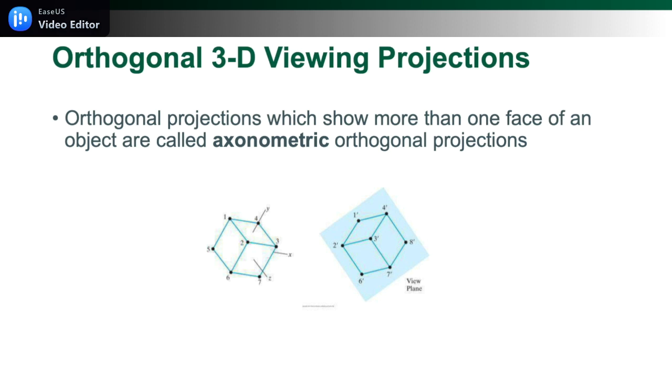In that, there's also another special kind, that is isometric projection, which is the most common form of axonometric projection, that are generated by aligning projection plane so that it intersects the principal axis at the same distance from the origin. So if we think of a plane, and if we think of those 3D axes, now you try to position the plane to intersect all of those axes such that the points of intersection are equidistant from the origin.